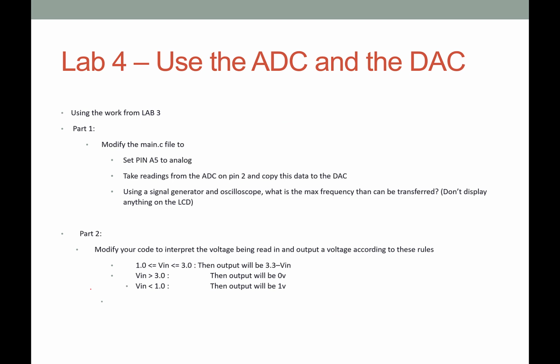Okay, so what about this next lab that is going to do a little bit of the analog to digital conversion and the digital to analog converter? What we're basically doing is using that same part that we did from lab 3. Now what we're going to do is we're going to do a couple of things. Okay, it says, what are we going to do? Well, we're going to set pin A5 to analog so that we can use, again,